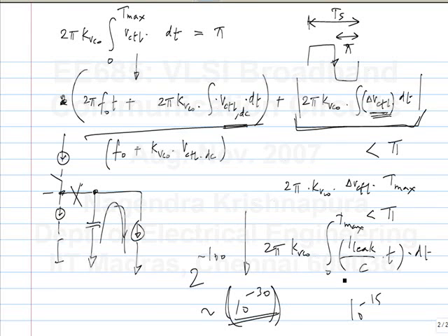Okay. Now, when you have normal random data with a transition density of half, the probability of actually crossing over pi is so small that this doesn't contribute anything to the bit error rate. Okay. So if there are no other errors, then there is a probability of 10 to the minus 30 that you will have the clock in the wrong place and so on. So the resulting bit error will be of the order of 10 to the minus 30 or thereabouts.